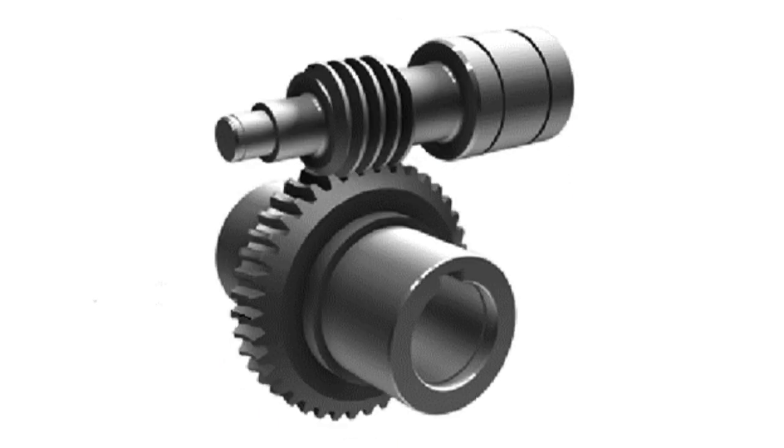Worm gear is a gear of high reduction ratio, connecting shafts whose axes are at right angles but do not intersect. It consists of a screw-like component carrying a helical thread of special form, the worm, meshing in sliding contact with a concave face gear wheel. Because of their similarity, the operation and efficiency of a worm and gear depend on the same factors as the operation and efficiency of a screw.